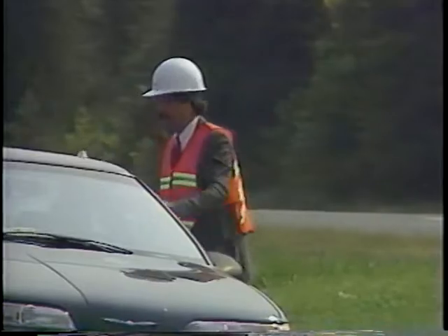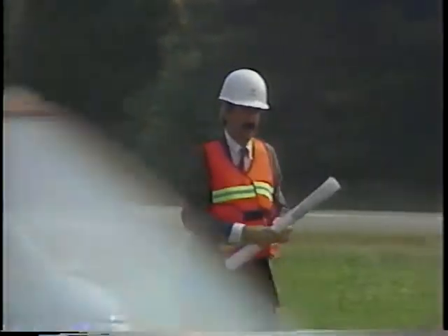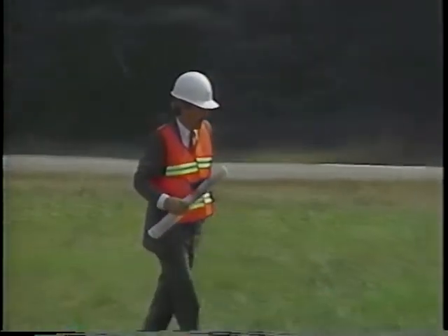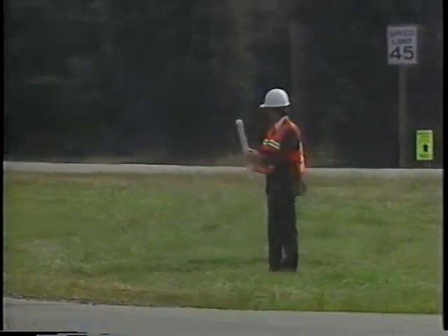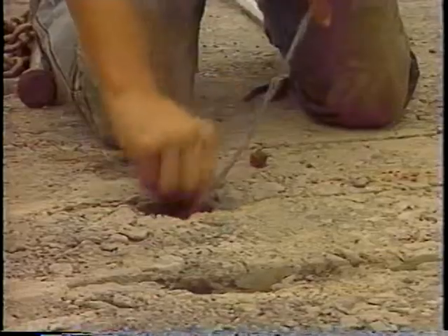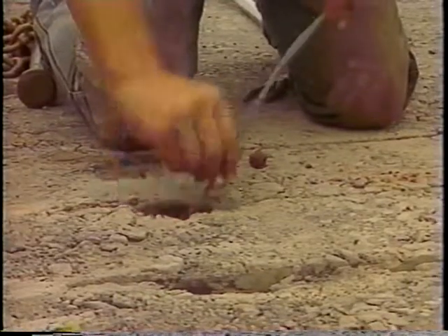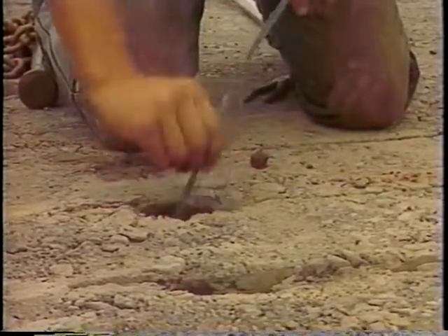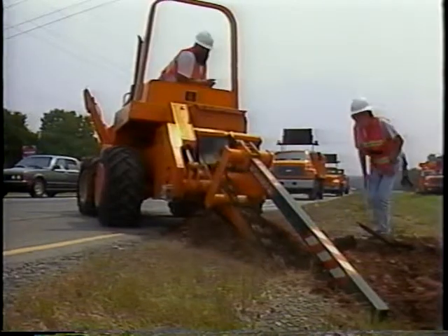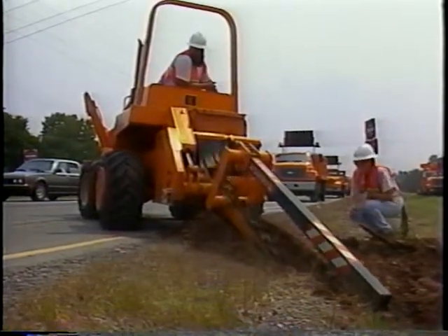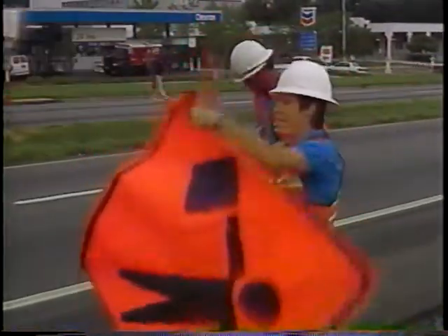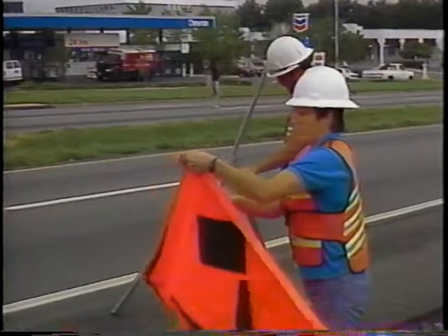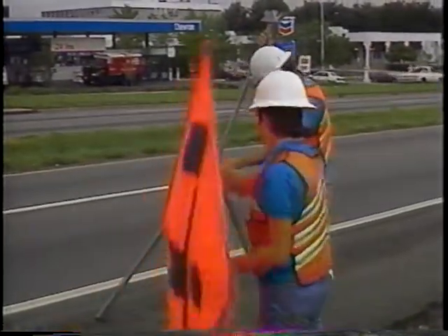Prior to finalizing the scale drawing, make a field visit to the location. Once on site, inventory the existing conditions and identify any potential problems. As a result of this visit, you should be able to determine the method for burying cables. Choose the types of equipment required for the installation. Identify the necessary installation permits and licenses. And finally, determine the method of traffic control and rerouting that will take place during the installation.